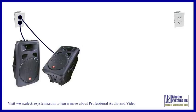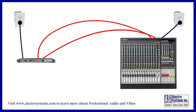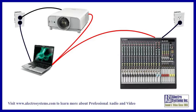The problem is more likely to be worse when the devices are plugged into different AC outlets. For example, AC-powered floor monitors at the front of the room connected to a mixer at the back of the room, or the mixer connected to equalizers or amplifiers in a separate room. Since the addition of computers and video projectors, these ground loops often occur when a computer input or output is connected to the audio mixer, or even more so when a video projector is added to the system.